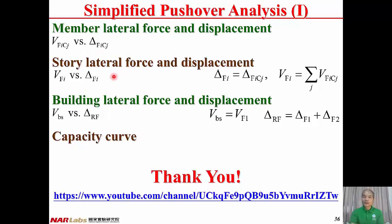And the second stage, we have to find out the force relationship in story level. That's the relationship between lateral force and lateral displacement, Vfi versus delta Fi. And delta Fi equal to delta Fi Cj, according to the assumption of rigid diaphragm. And Vfi equal to summation of Vfi Cj.